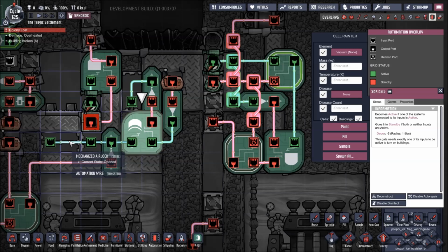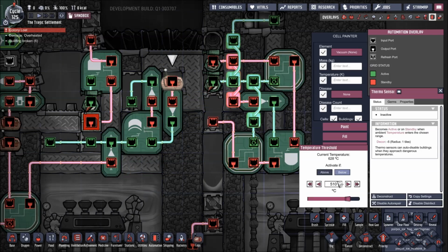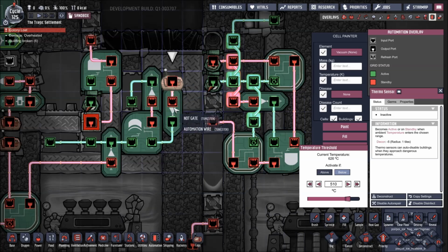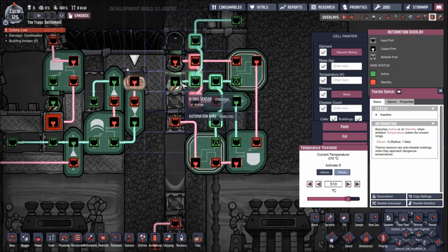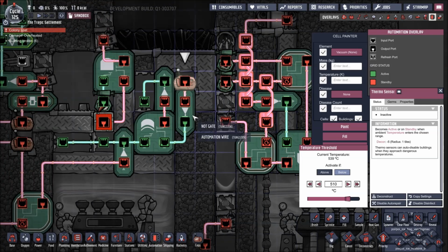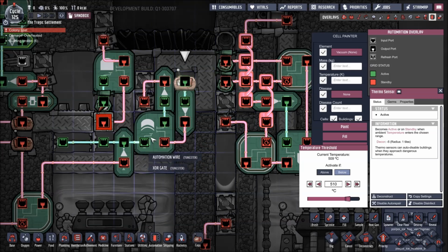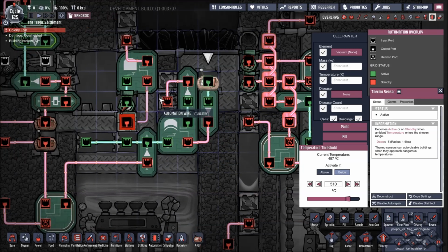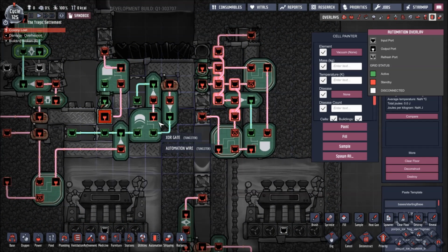So when these doors close, that's going to be an inactive signal. And then when this drops below 510 degrees, it's going to be an inactive signal, which it does frequently, you can see, because it's transferring its temperature from here over to the oil. And then, you know, it drops below 510, and then that'll be a NOT. Now, when this signal's inactive, this door is going to remain open, and we won't be transferring any temperature over to the oil. Now, this system isn't necessarily needed.